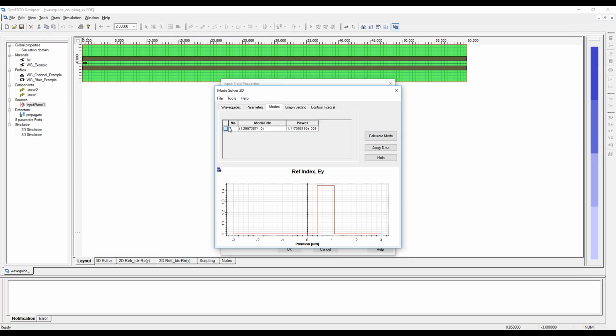And you'll say, okay, when it's one waveguide by itself, it only supports one mode, one polarization. But as you bring 2 of them together, you get a super mode, a different structure. You can add up the 2 modes of the 2 independent waveguides to create 2 new modes, one symmetric, one asymmetric.